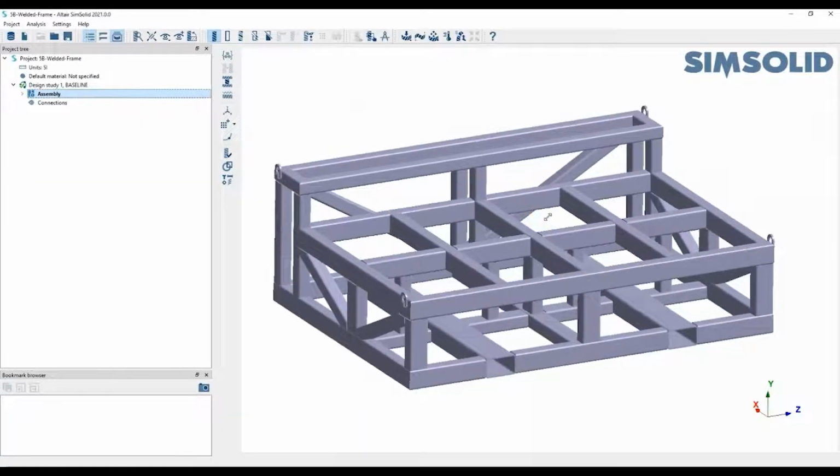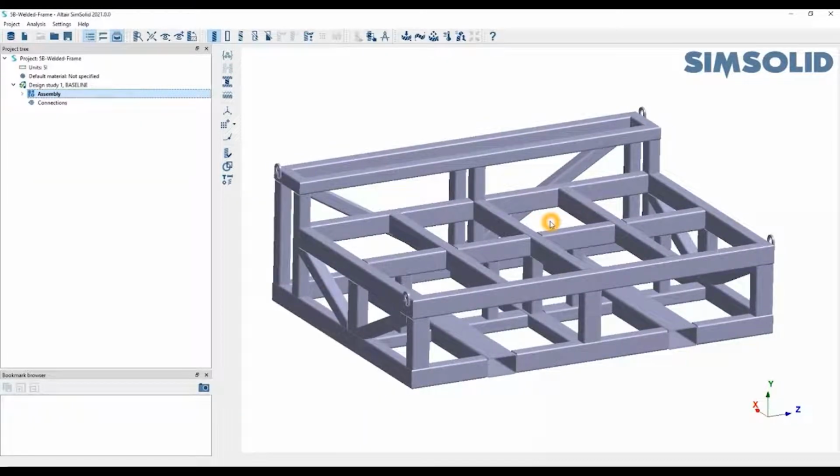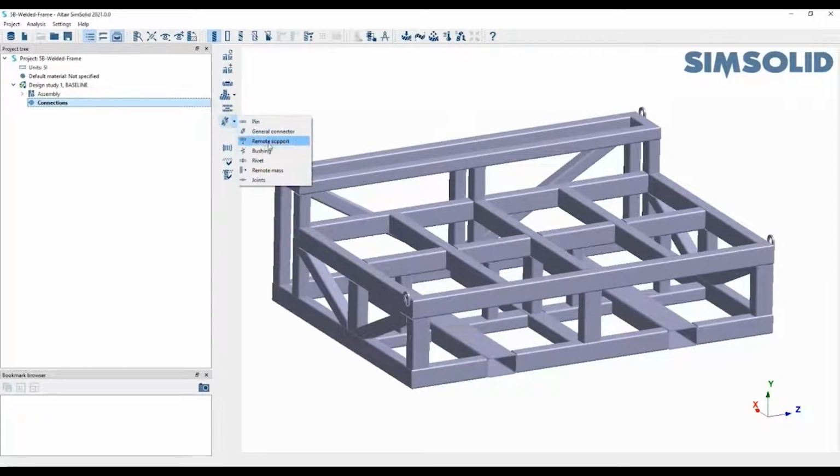Now, the workflow we also recommend is that if you know you have an amalgamation between welded parts as well as bonded contacts or connections that you want to implement in, we always recommend doing your welded contacts first. So within SimSolid, you can create spot welds or seam welds or adhesives, just so you know that you do have lots of different virtual connectors that you can also use.